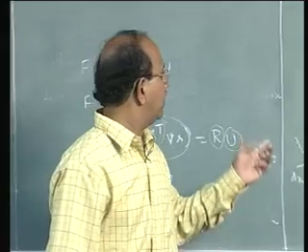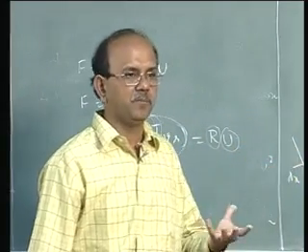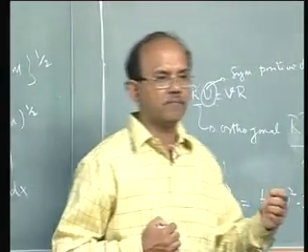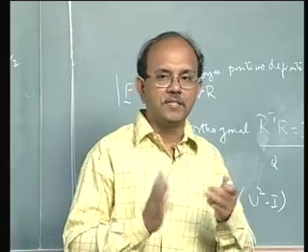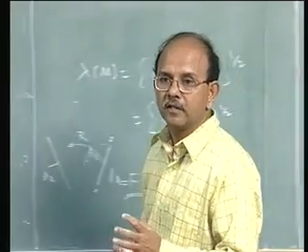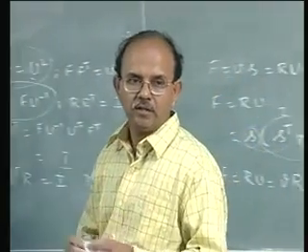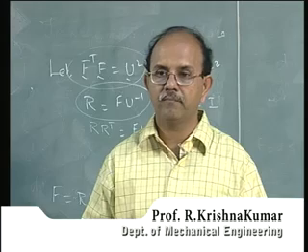When, on the other hand, you use VR, what it simply means is that first you rotate it and then apply the stretch. So by this decomposition, we are clear about that component of F which causes stretching and that component of F which causes a rotation.